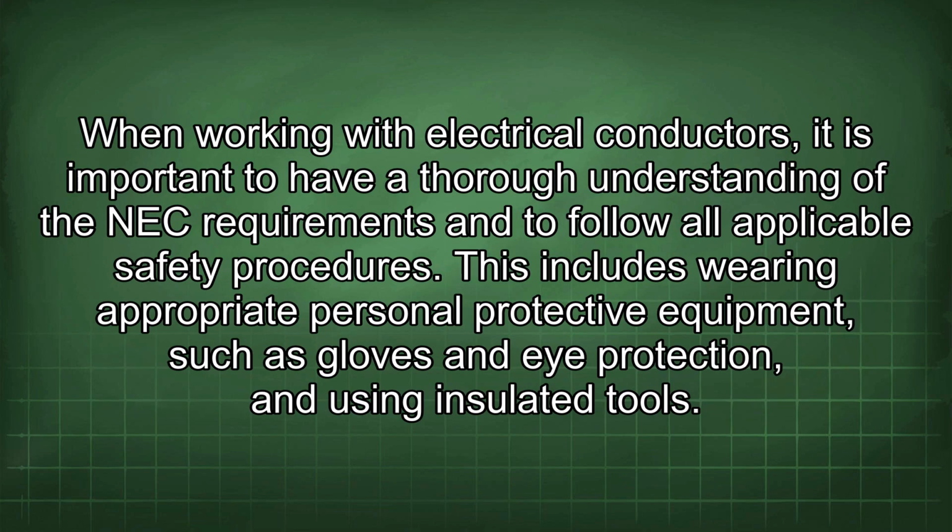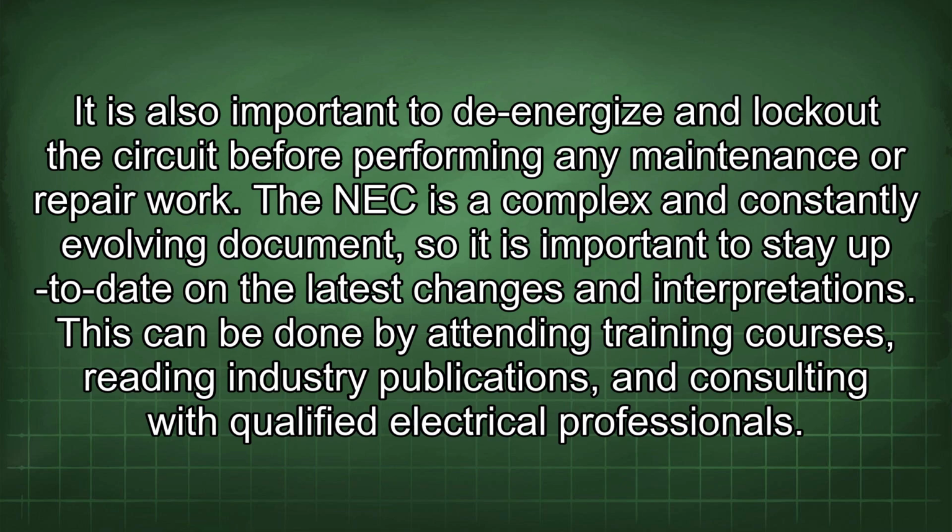When working with electrical conductors, it is important to have a thorough understanding of the NEC requirements and to follow all applicable safety procedures. This includes wearing appropriate personal protective equipment, such as gloves and eye protection, and using insulated tools. It is also important to de-energize and lock out the circuit before performing any maintenance or repair work.